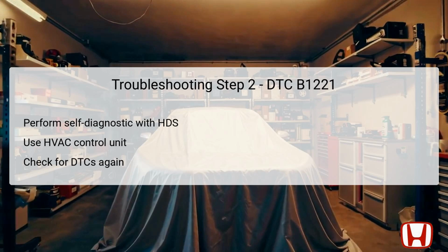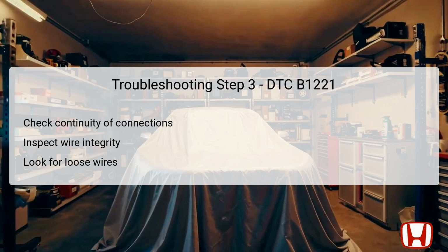If it remains, further investigation is warranted. If the DTC B1221 persists after self-diagnostic, it is essential to investigate the wiring and connections linked to the rear mode control motor circuit. Check for continuity using appropriate testing equipment.